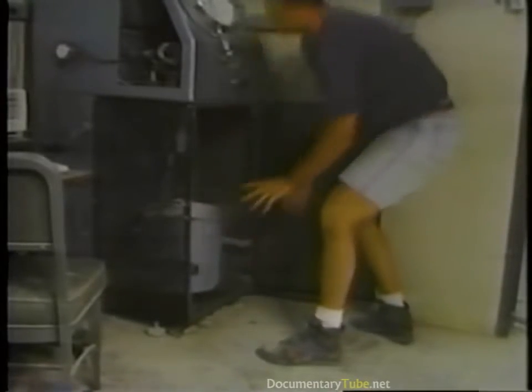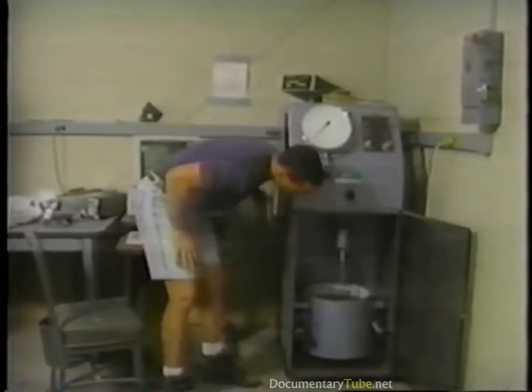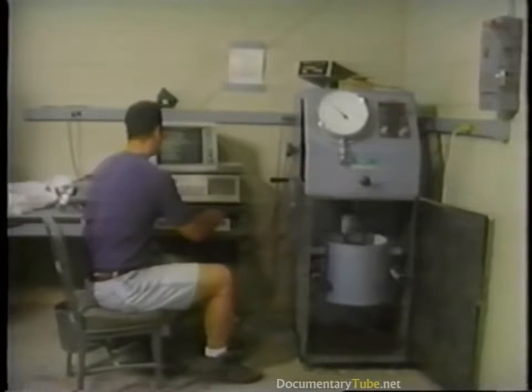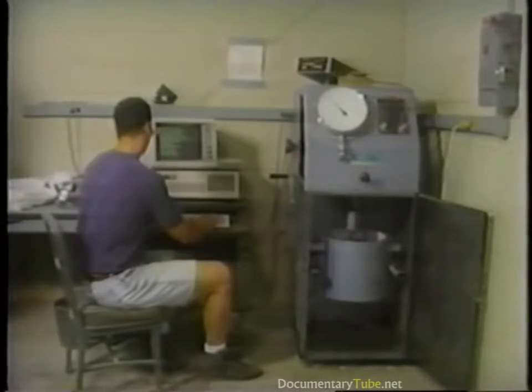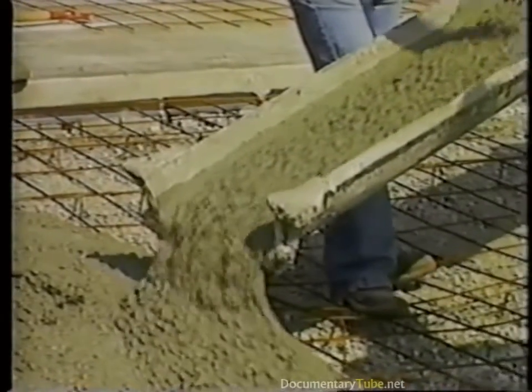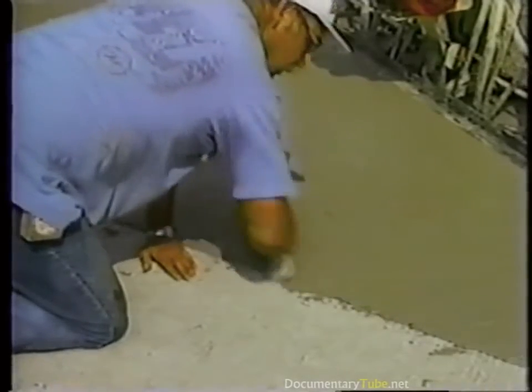Researchers use larger equipment, such as this Tattersall rheometer, to measure the properties of mortar and concrete. The rheological equipment can be used to measure the initial resistance to flow, which is referred to as yield stress. At the time of setting, the yield stress starts to increase abruptly, and the ability to flow is lost. Researchers are interested in flow characteristics of concrete and what leads to set in the concrete.